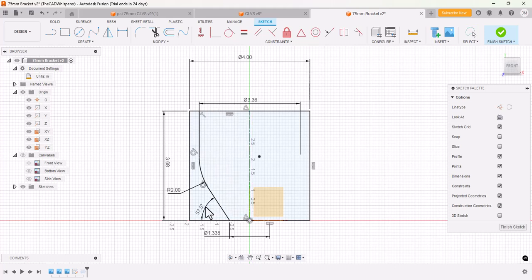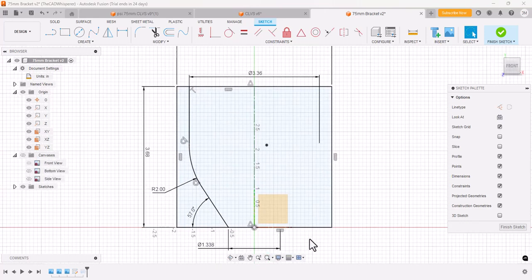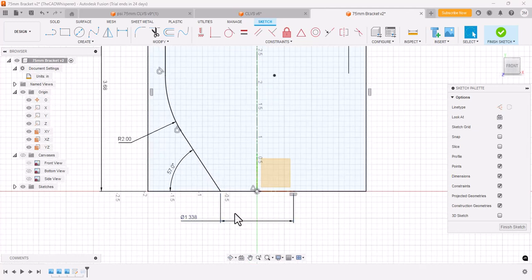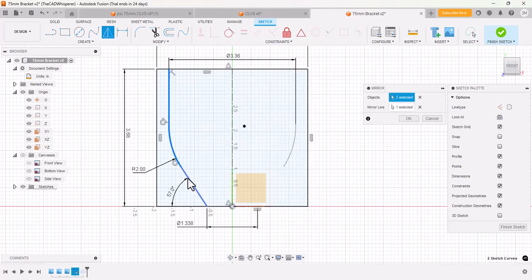I need to check on this angle dimension and see what it was. Alright, I'll turn off the graphics. Now I'm kind of curious about where this dimension came from. Several different things we need to think about here. The part might be a combination of inch units and metric units. Actually, let's measure, and to measure that first I'm going to mirror that to the other side. So I'll mirror this line, this arc, and this line. Now make sure this is tangent on both ends of this arc, tangent to these lines.